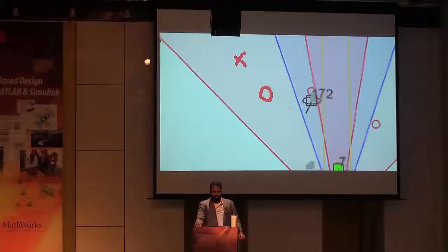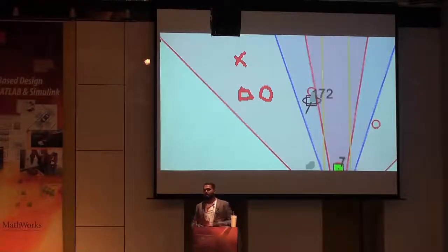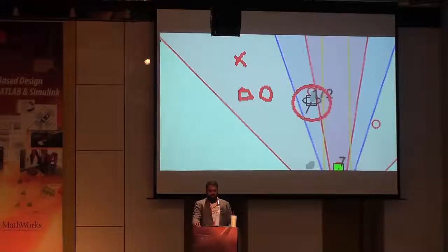Radar is better at range finding. So you could say that the probable location of the object is somewhere around here, because you're using the most accurate axis of the objects in question. And that's what this tracked object is. We're applying sensor fusion in that way. We're applying the assumptions about the two different sensors to find the most probable location of that object.